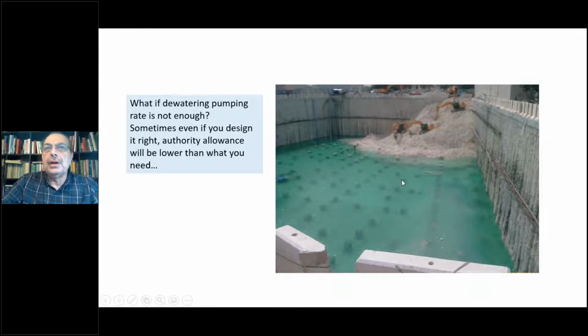But the discharge levels that we had should be allowed by the authority to some discharge points. But unfortunately, when we reached the maximum level of excavation, there was a disruption in the discharge points released by the authority and delay of approvals, which made the dewatering system unable to discharge the water away from the site. This is in the middle of the city, so we cannot discharge to the sea, and we need to discharge to specific drainage points.